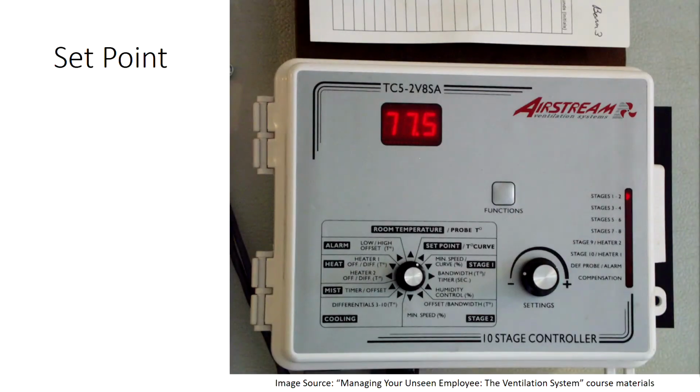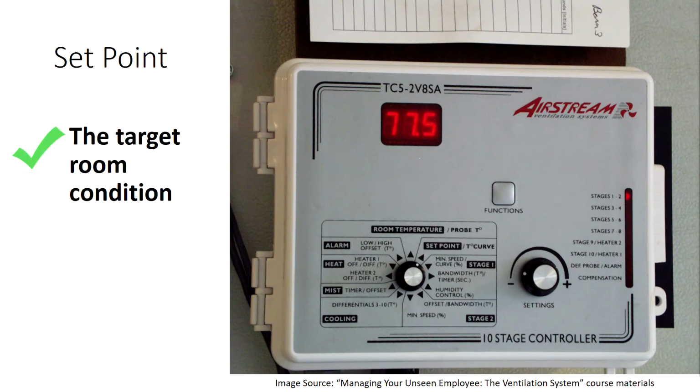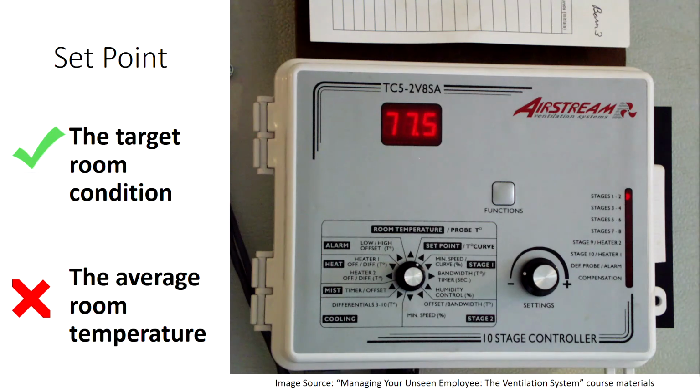Regardless of controller type, set point is the term we use to describe the target room condition, but it does not necessarily mean the room temperature. Most modern controllers allow you to set a set point, and the rest of these settings adjust around it. So while the set point is an actual temperature, three key settings that we're going to focus on in this video are typically temperature ranges with respect to the set point. After a quick review of these terms, we will go through some simulations to show how these settings can work together to influence room temperature and save energy.